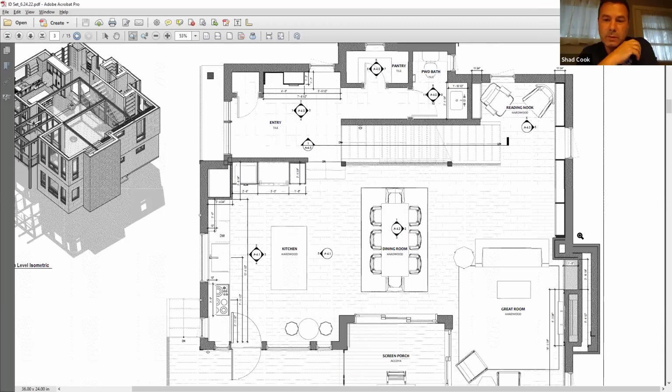On the outside, if the cantilever isn't an option but we can get through to that soffit above the bookshelf, that might be another option. If that's 12 inches in depth, we can try to keep a 10 by 12 duct up through there, if that's even feasible. But if that's all CMU, it looks like that's a pretty tough area to go by.